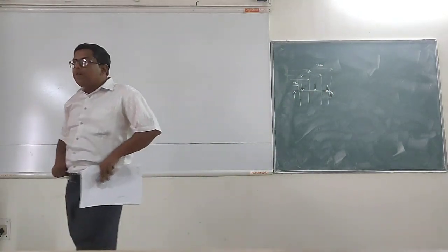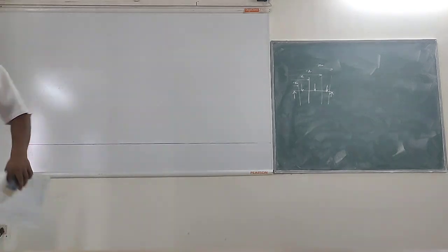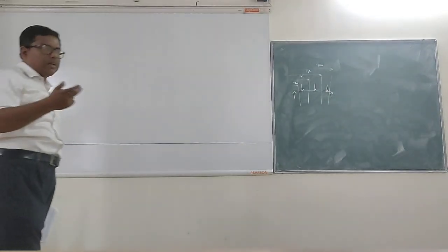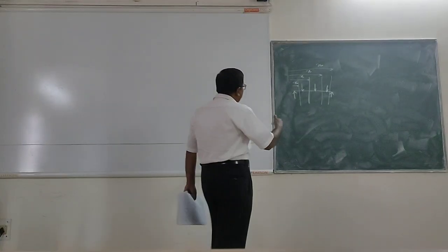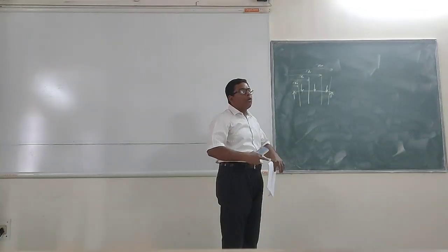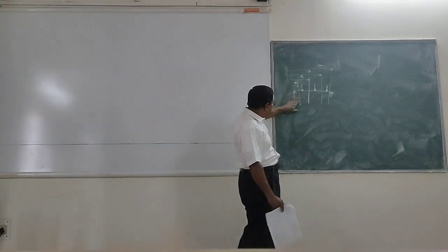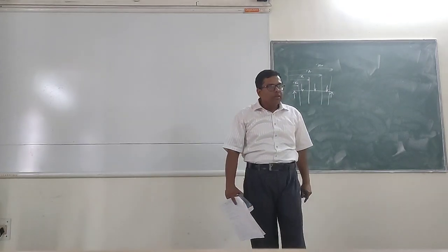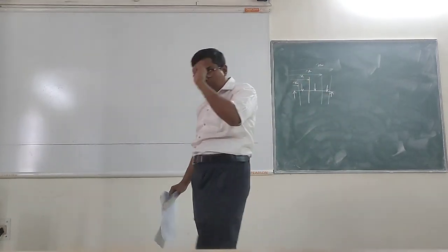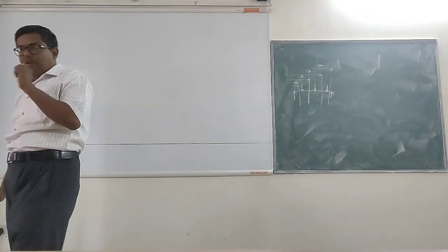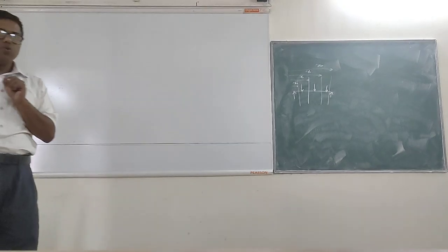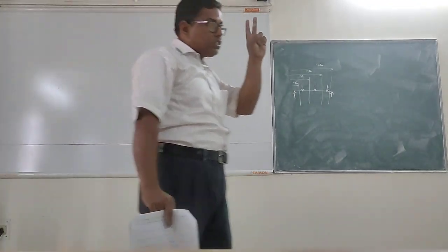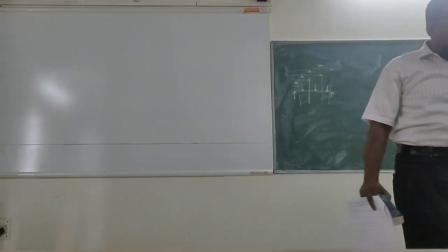So that means, when the beam is subjected to 3 point loads, you need to have multiple moment equations. Like this is the first moment equation, second moment equation, third moment equation, fourth moment equation. All these equations will give rise to 2 constants each, because it is a double integration method.